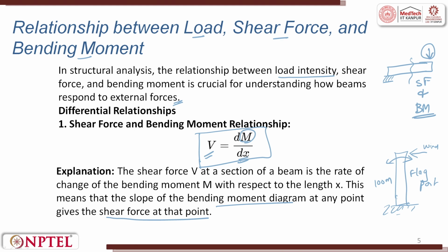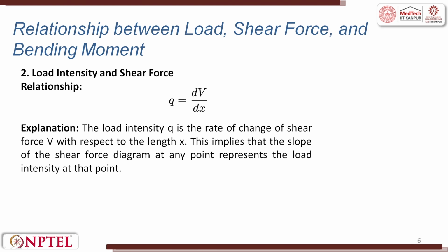So what is the relationship between load, shear force and bending moment? The relationship between load intensity and shear force is q = dV/dx. What is q? q is the load intensity, the rate of change of shear force V with respect to x. This implies that the slope of the shear force diagram at any given point represents the load intensity at that point.